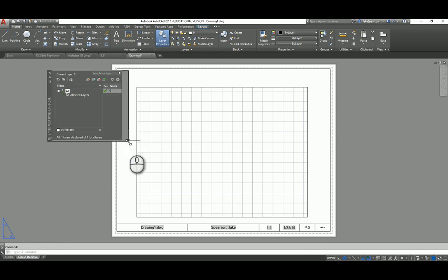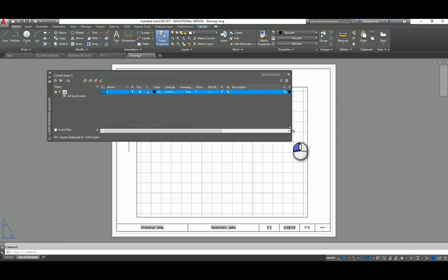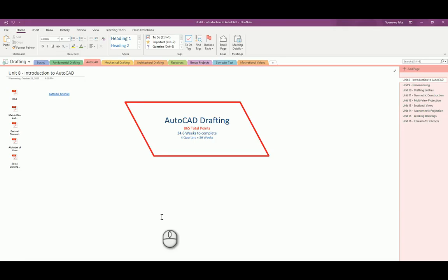Make it easier on us because we don't really want to keep typing all of that in there. But before I go over that, let's just simply explain something to you again. A lot of you guys will go over and dimension a bunch of stuff, and you'll open up your decimal dim style, but by accident you'll click the metric dim style, and you will dimension it, and your dimensions will look massive. The reason why is because you have chosen metric and not decimal dim style. If I select it once or just scroll over, it describes everything.